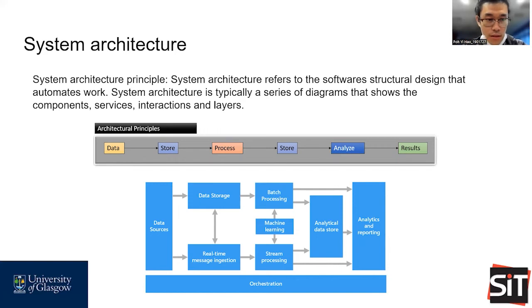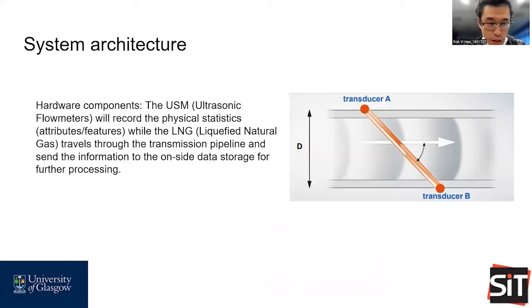So for the liquefied natural gas process, it will first obtain the measured data through the hardware components, the ultrasonic flow meters, where it will record the flow of the liquefied natural gas through the pipelines.